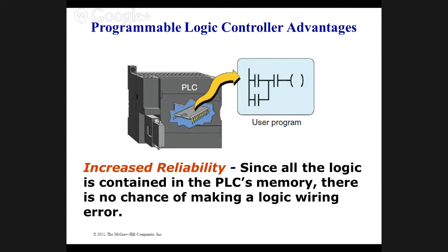Well, it was replaced with a PLC, and instead of running all those wires, we run a single small blue hose, one wire, to communication modules mounted throughout the machine, and we eliminated all that wiring that was giving us problems in that machine. The control panel was separate from the machine, and what we did is we eliminated 90% of the wiring on the machine with one blue hose in a PLC program.